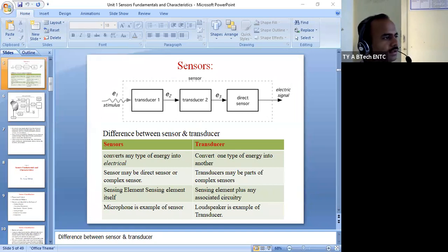either analog or digital format, and whether they are contact type or non-contact type, that is, directly immersed into that particular environment or substance. Any measurement of temperature needs to be inserted into the water to check the temperature of water or boiling water, whatever. So like that, this is the contact type. Non-contact type, like an air conditioner, has a temperature sensor which is not directly in contact, but it is there in that case or body, and that particular sensor is capturing the temperature from the surroundings, and according to that it will generate the reading.